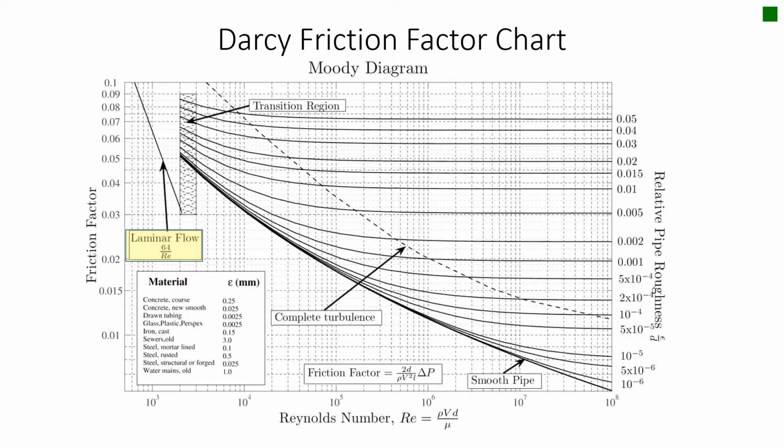So if we look at our plot in front of us, on the y-axis is the friction factor. In this case, I'm dealing with Darcy, and it's a function of the liquid Reynolds number, Re. Okay, and we have a laminar flow region, which is given here on the left-hand side. And in our case, our friction factor chart includes the relationship where the friction factor is just a value of 64 divided by the Reynolds number.